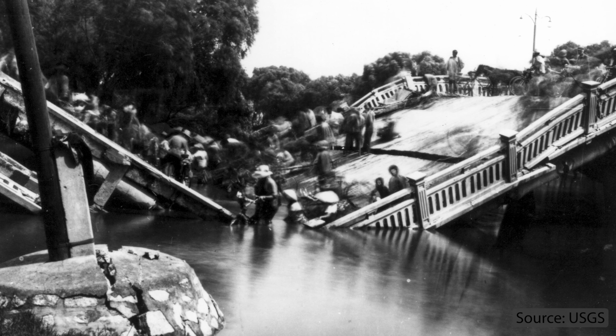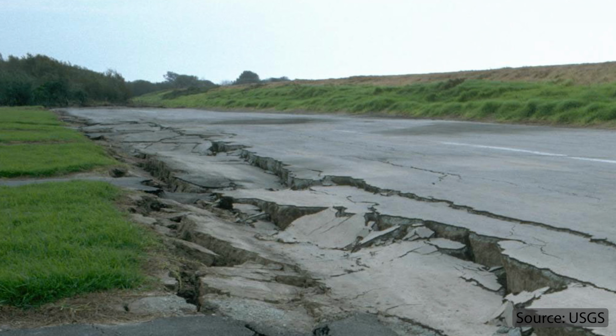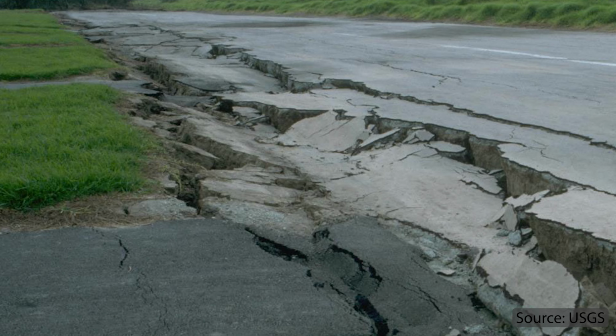To design bridges to resist seismic forces, you're right, it is a big subject right now. Probably the foundation issues are the biggest in many of our cases. The liquefaction and some of the just poor soils that exist in Western Oregon in particular, they actually drive the cost of seismic design. It is a big process.